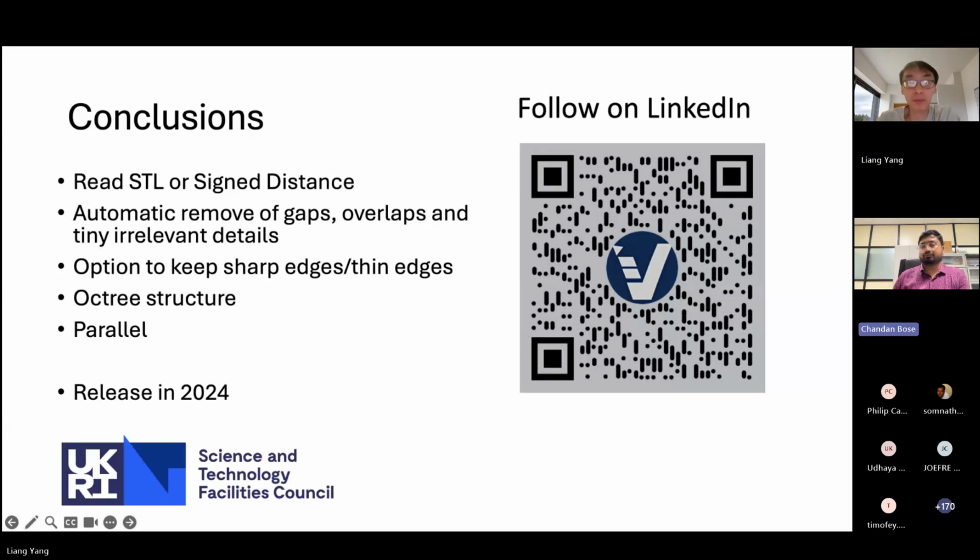Another follow-on question was, can you use adaptive mesh refinement? Yes. Currently we have octree-based refinement. If you have an adaptive mesh on a particular region of interest, because most of them are voxel based, you just divide by half, splitting one cell into eight. That's the type of thing.